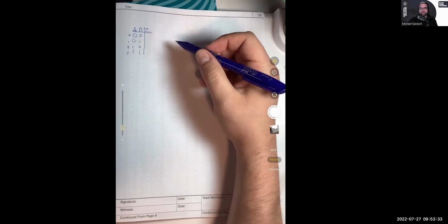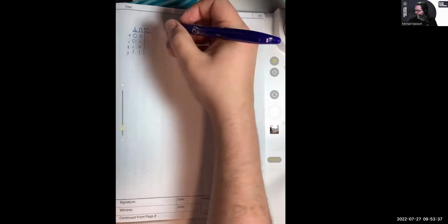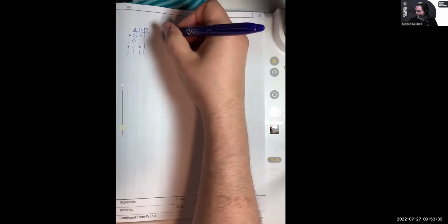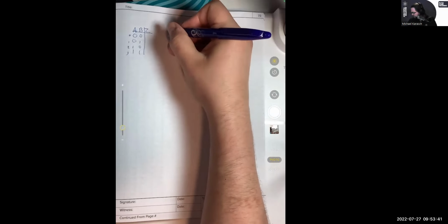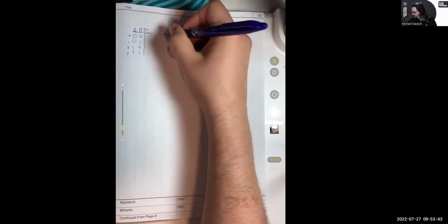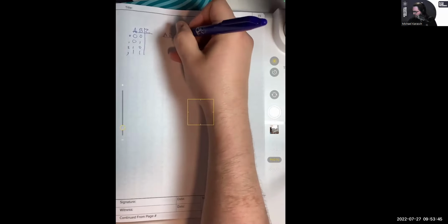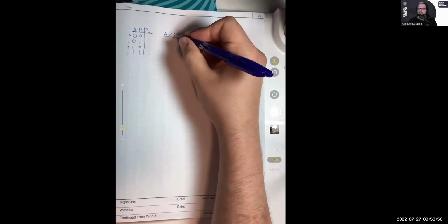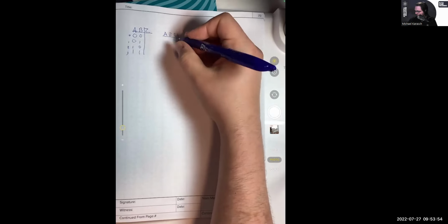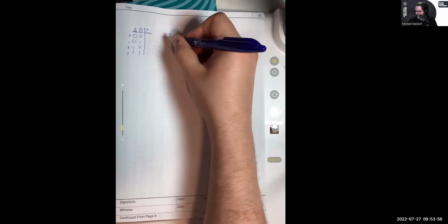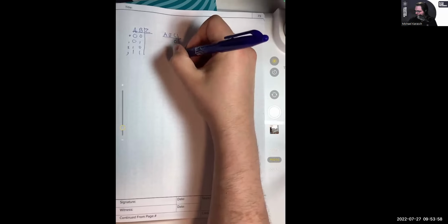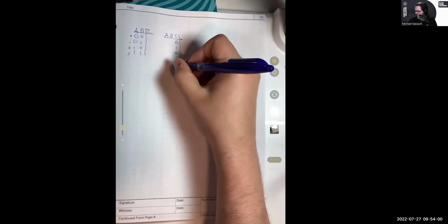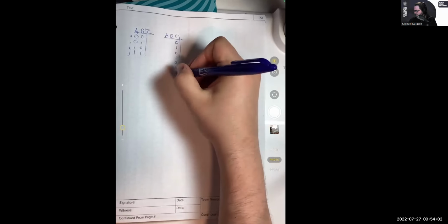The cool thing is, though, you're like, but my binary is not so strong, Crash. That's okay. Don't panic. I'm going to show you a trick. So if I want to make a 3-input truth table, A, B, C, here's the little trick. Watch this. In C, the far right column, I'm going to alternate every one. I'm going to go 0, 1, 0, 1, 0, 1, 0, 1.